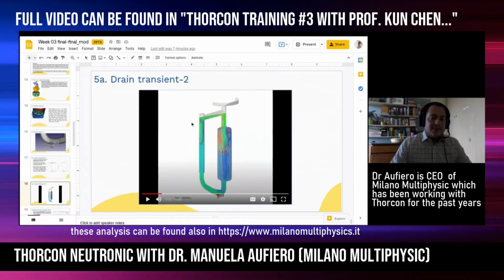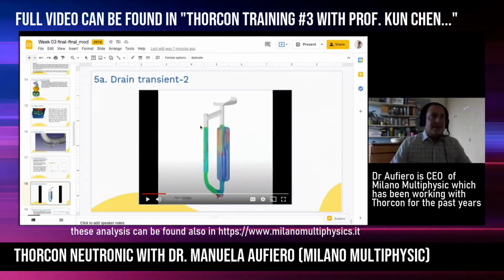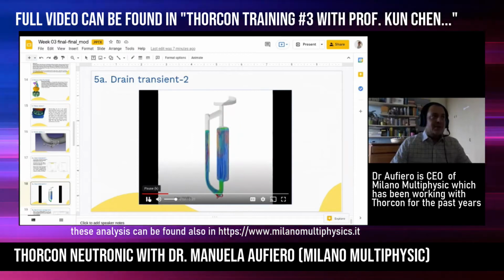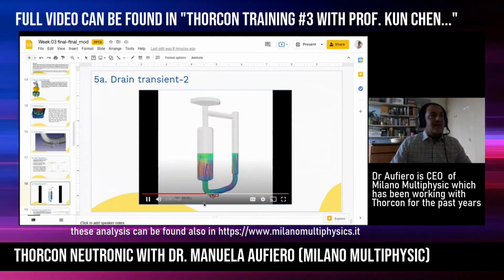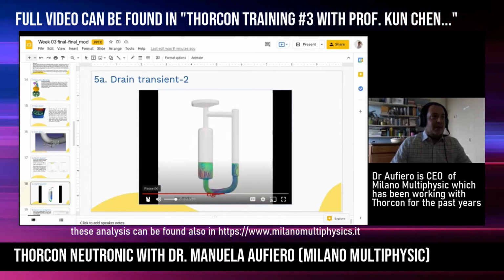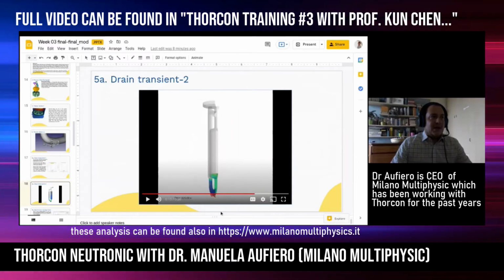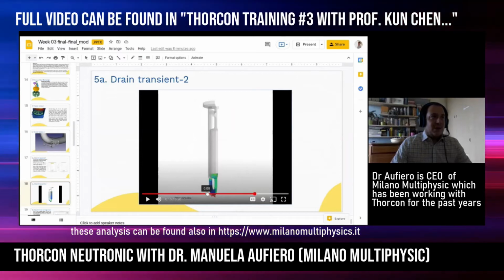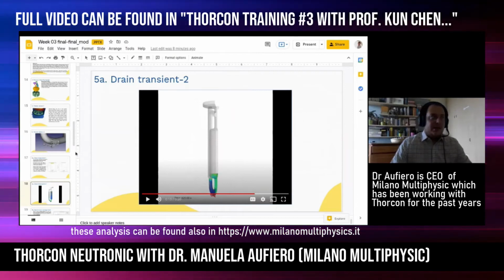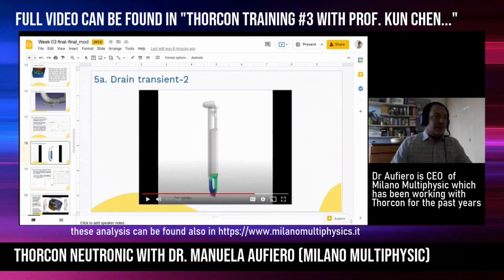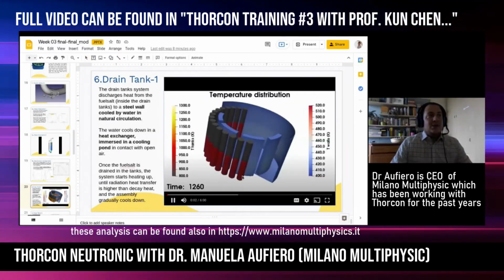Then the pipe completing the primary loop below the valve. Then the primary heat exchanger is emptied. And finally, the core empties. These all happen in approximately 600 to 700 seconds. The flow of salt is stopped after 700 seconds, and all the salt is in the drain tank. The salt in the drain tanks evacuates heat mainly due to radiative heat transfer.